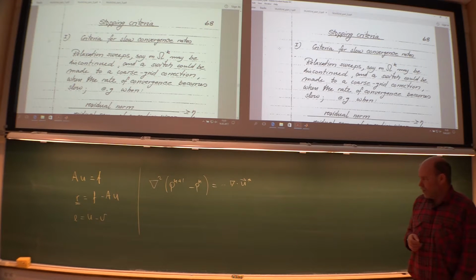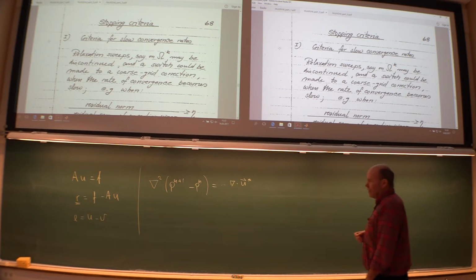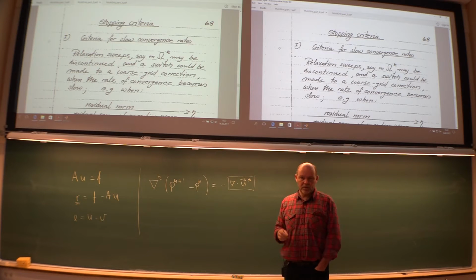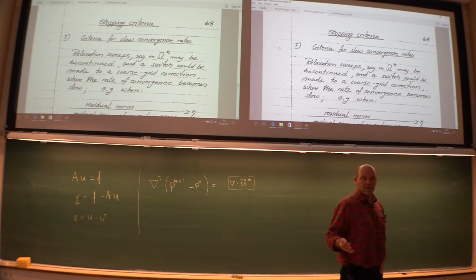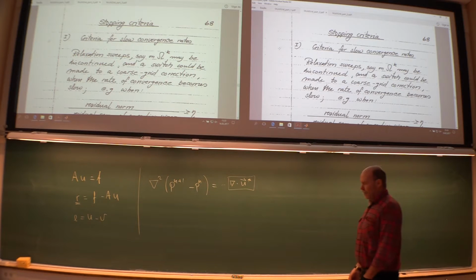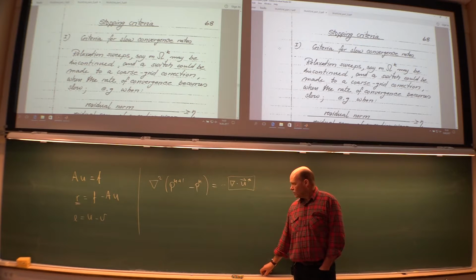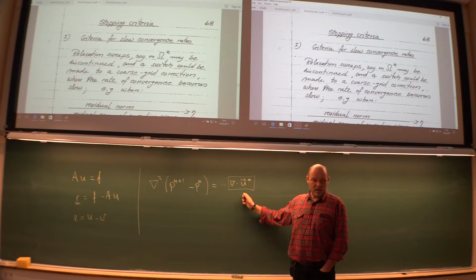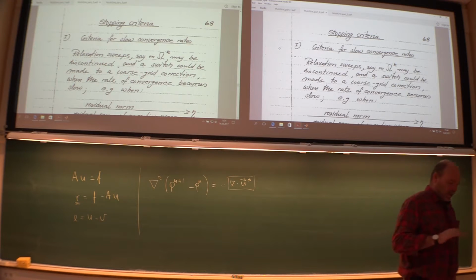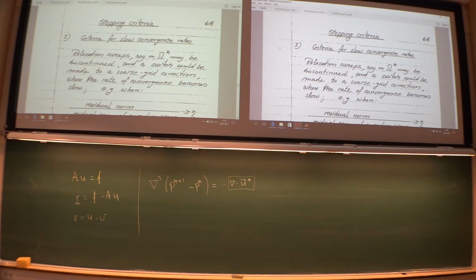And there you have a beautiful stopping criterion. You evaluate the divergence all the time from the freshly updated velocity field. And the divergence is a quantity with physical meaning. If the divergence is so and so small, then you can tell how good your solution is. So here you definitely have the possibility to decide your error level with a physical meaning instead of just using the residual.